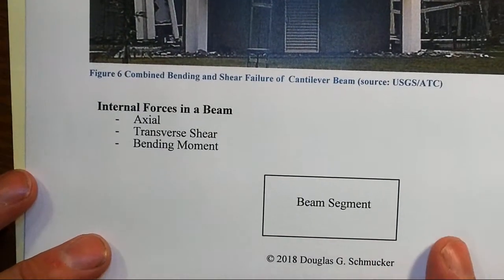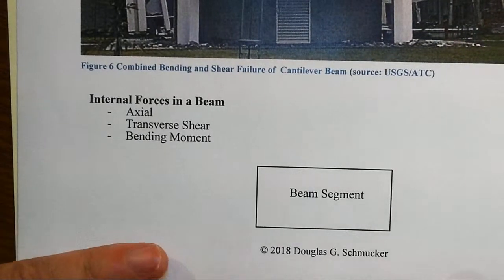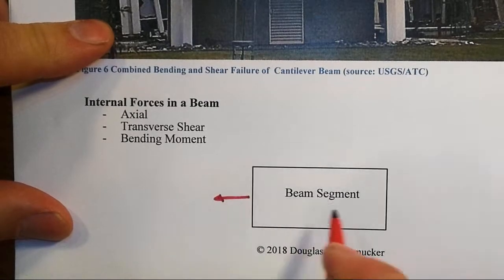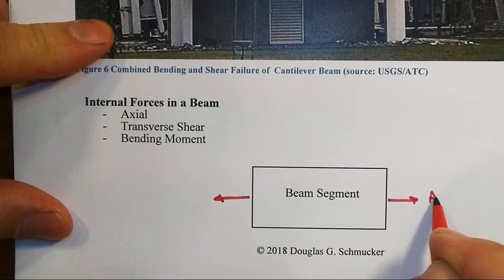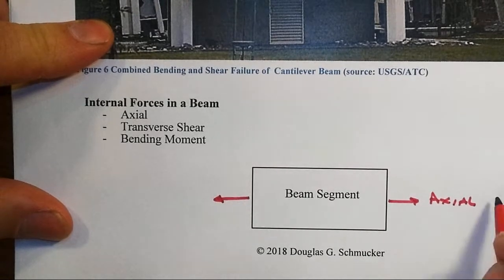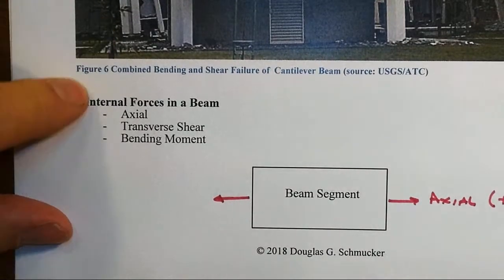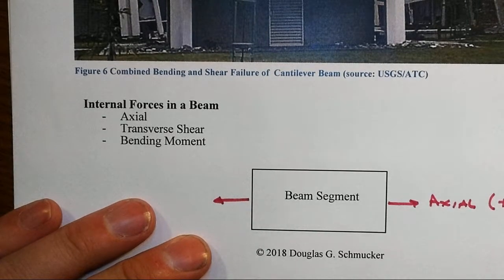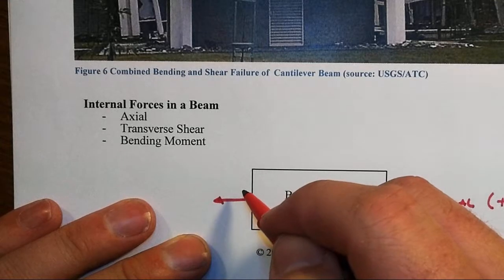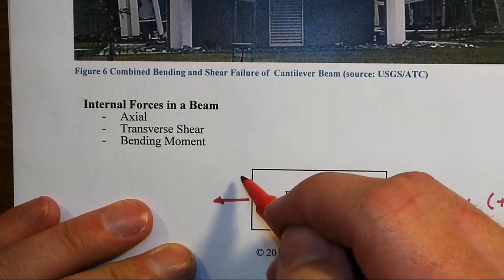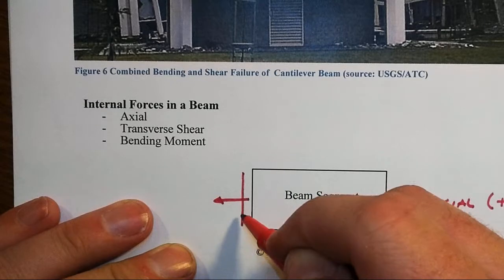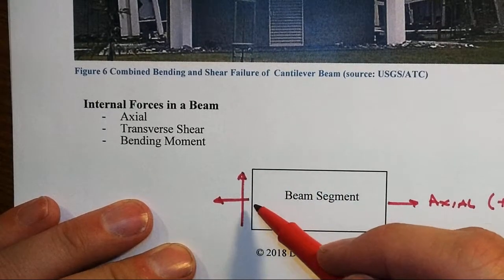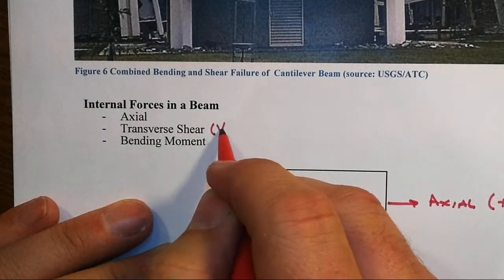Right? So let's get into more precisely talking about what goes on in our model of beam behavior. We've already talked about axial forces, and we would tend to show positive being in tension, not always, but it's a pretty common thing to do in most computer modeling. You'll see that. Now, transverse means perpendicular to something. Well, perpendicular to the long axis, or ultimately, shears are always parallel to something, parallel to this surface. And the symbol that we use for shear is capital V.